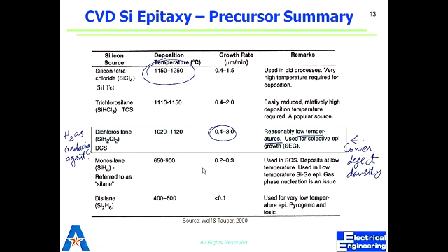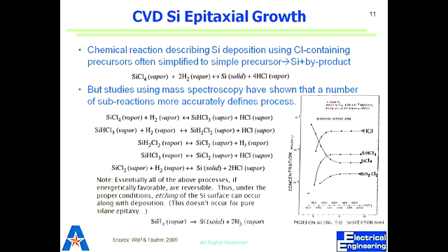Do we do anything to get rid of the chlorine? The product has to be treated before you can't just throw it out in the air. No, I mean from the reaction. So you need chlorine incorporated there or not? You don't. It goes away in gas form. But do we do something to facilitate? Like in RIE, we use chlorine to get rid of the intermediate products, right? So do we do something here to get rid of the chlorine, or it's not required? I think it's coming off as HCl, as a gas, acidic gas. You just sweep it away.